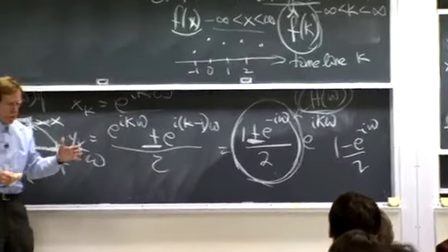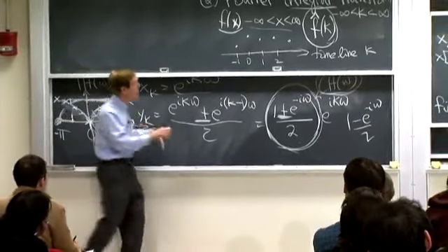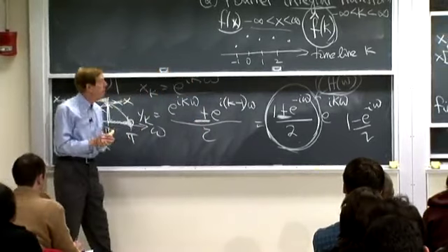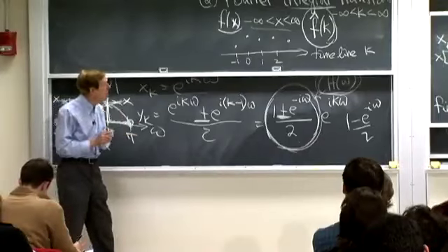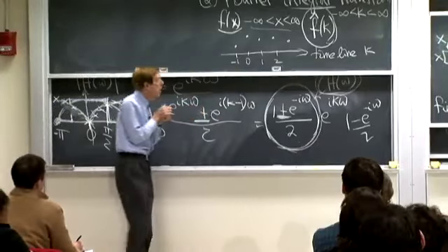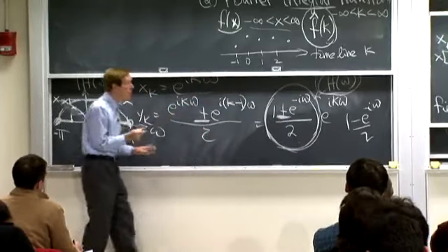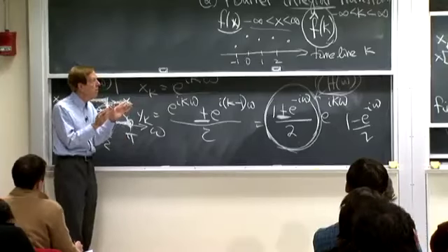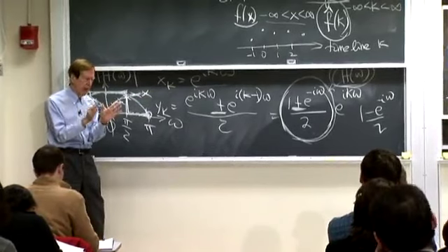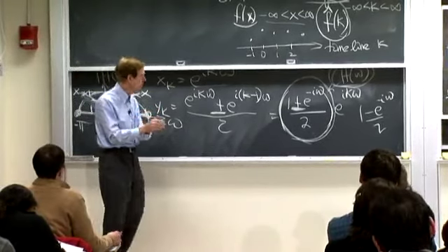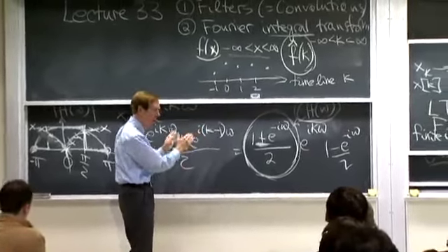Let me go back to the averaging filter. The averaging filter would smooth out the bumps, because it would average neighbors, and that's a smoothing process. As we see here, it's a process that kills high frequencies. Now, what is this visualization I want you to think of? Think of a moving window. Here's the input. Now I move a window along.